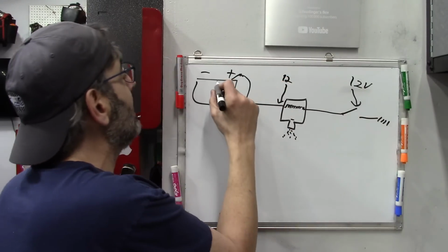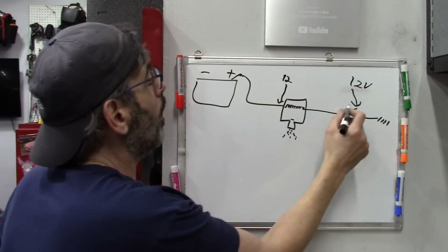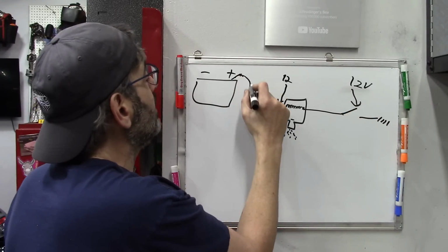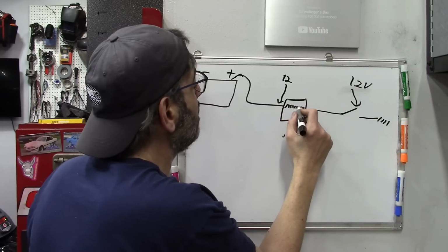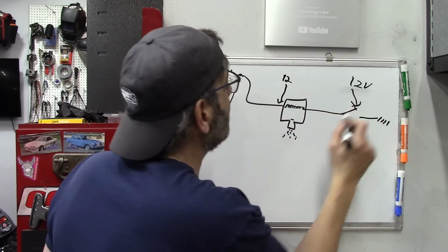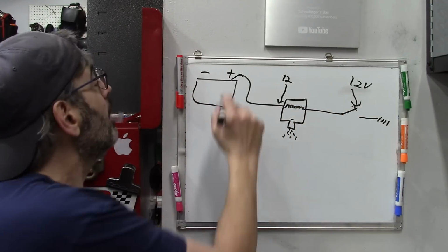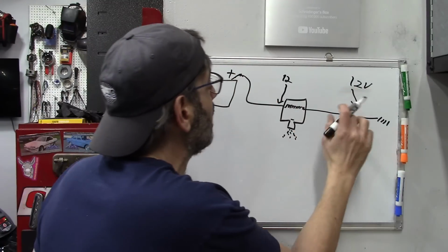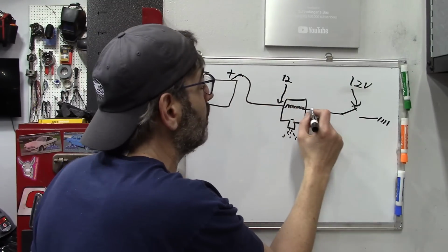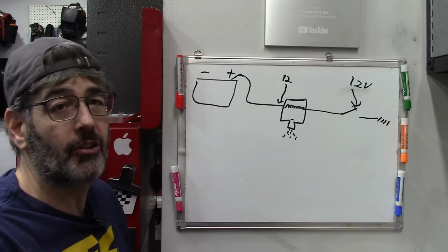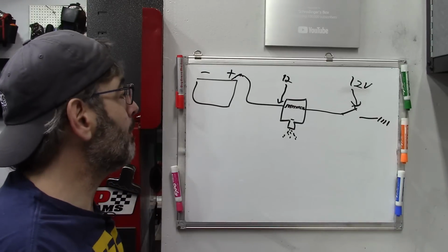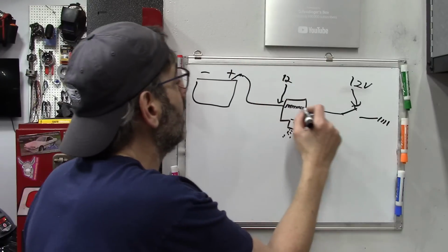What is our voltage here on this side of the injector? 12 volts, right? It's like water pressure. The water can't flow. So it goes here, it's filling up our coil, it goes here, but it stops right there. It's like a hose that's capped off. So the pressure is the same all the way through. What is our current through here? How many amps here? 0. No amperage, no current, because there is no flow.